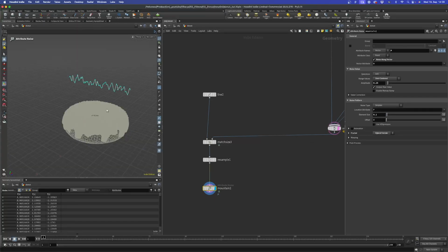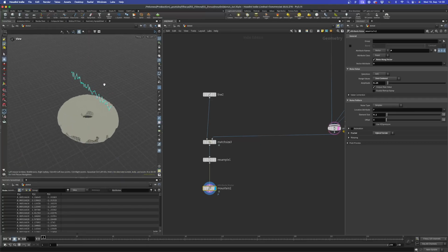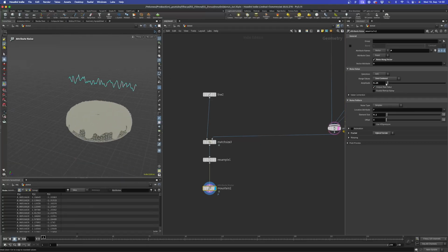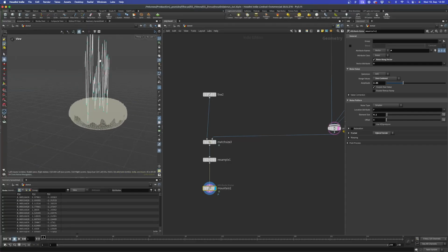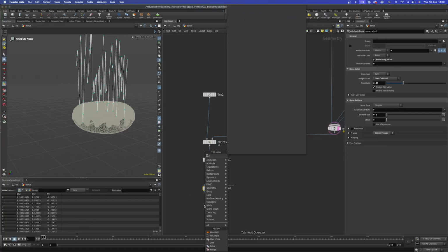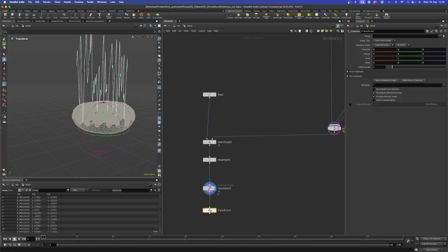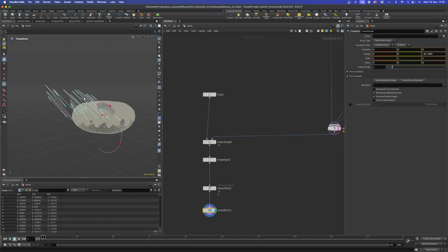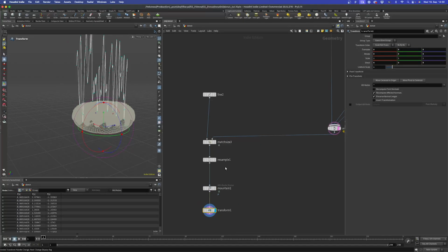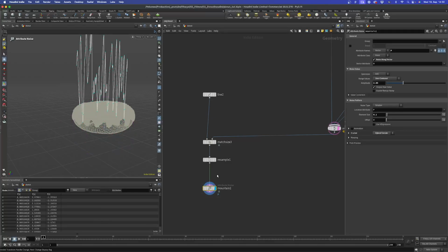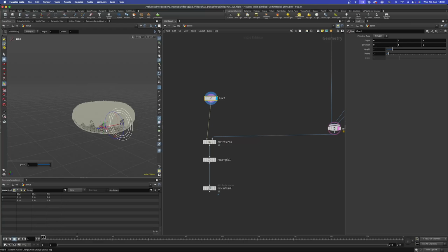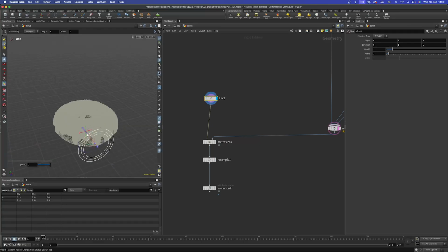And you see it's going up and down. This is what I don't want. I really wanted it to go from left to right. I mean, I could simply come in here and rotate the entire thing, but we shifted it up already. So the smarter thing to do is to adjust the normals from our line before, so that they will basically look in the X direction.